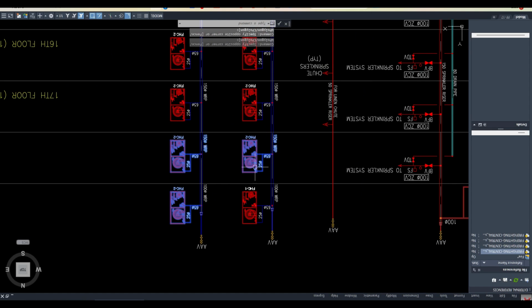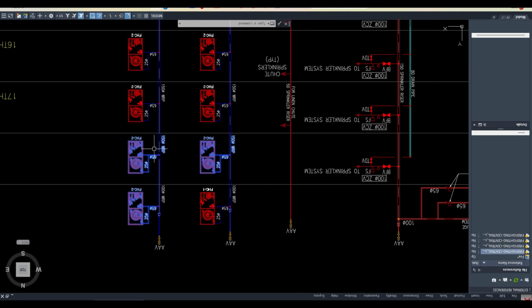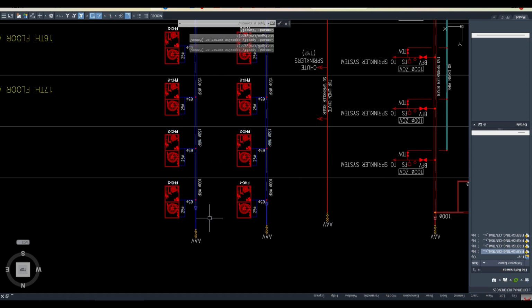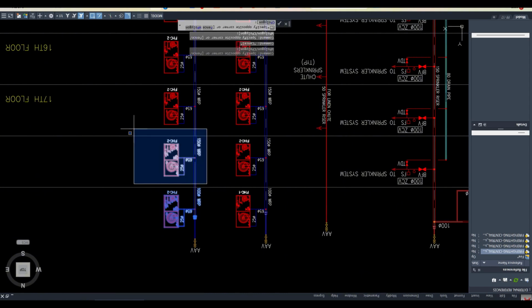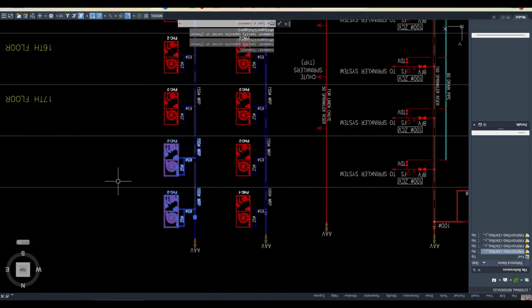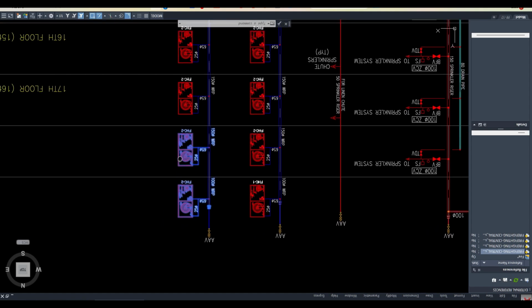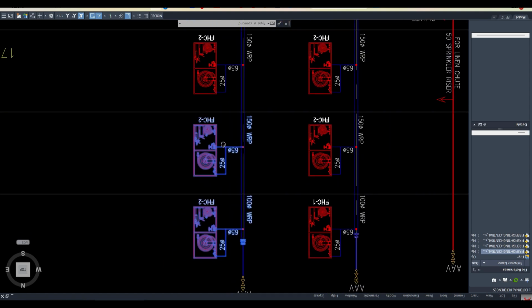Now, the consideration while designing this, you don't have to remember it, I'm just giving it for reference. When you're designing this fire system for the remotest location, the remotest location is of course on the roof. Then you have to consider one more as an extra safety factor: the floor below the last floor should also operate, so you have to count it. When both of these fire hose cabinets are working, what is the maximum demand that will come?